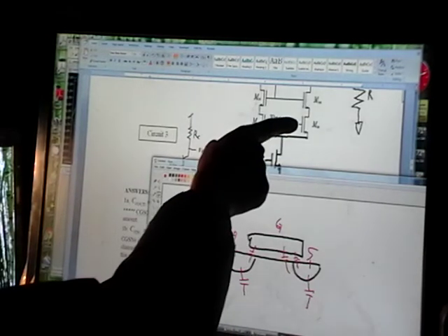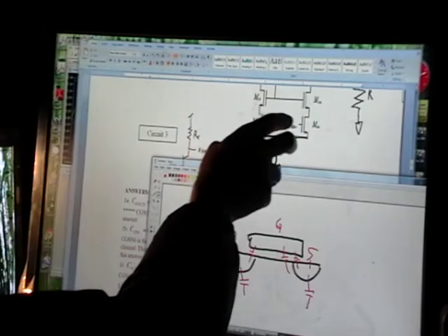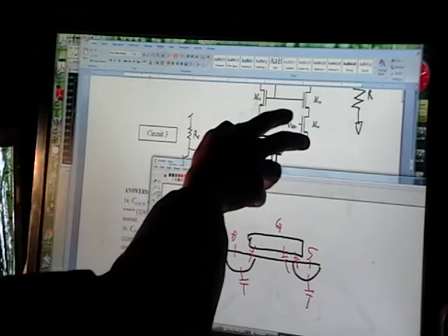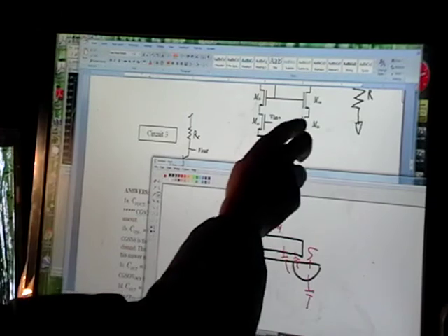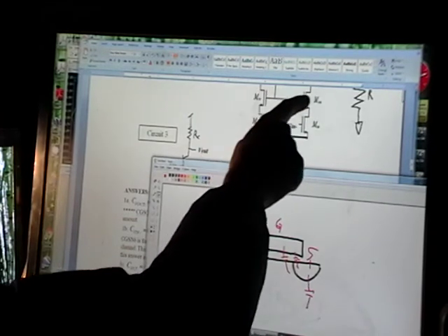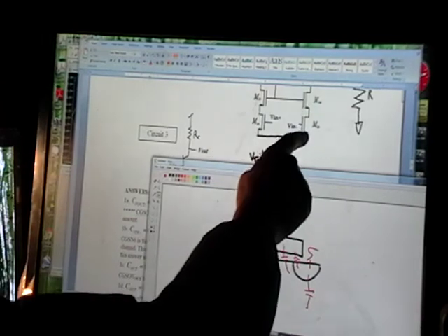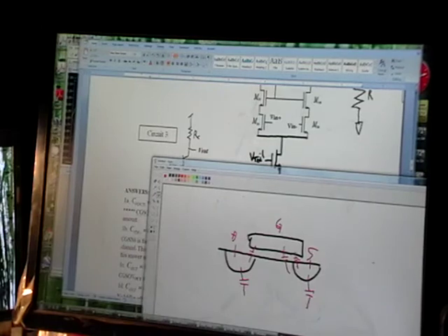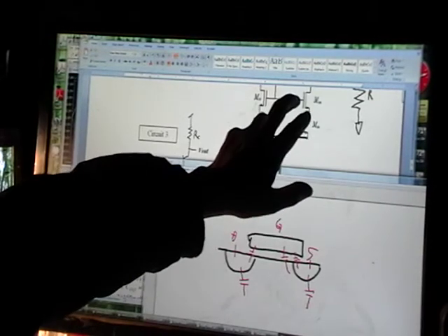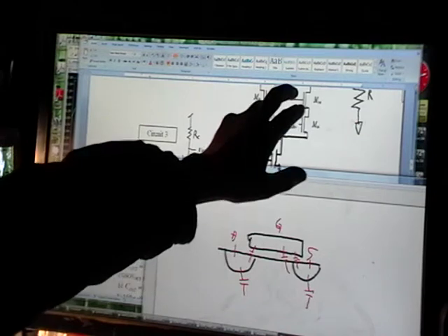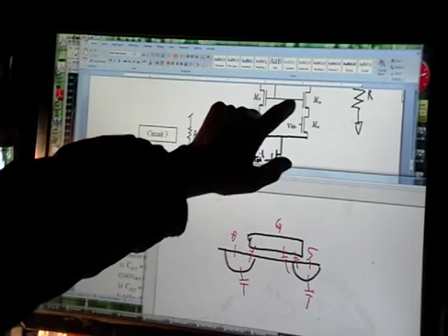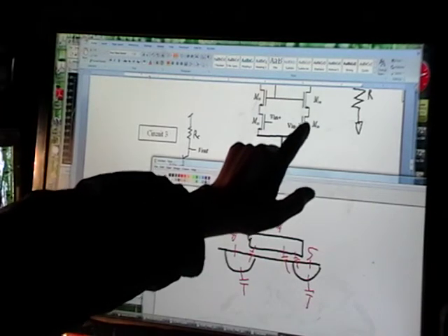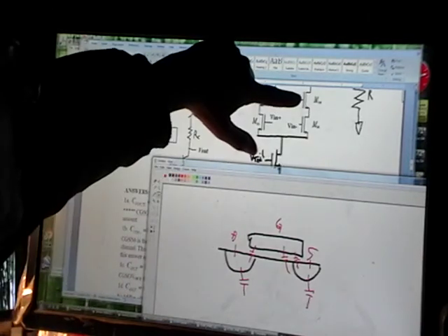And in the cascoded case, when V in minus goes up, that's just changed the VGS of this transistor. Okay, so if this goes up, VGS increases, the current through here increases. Now this transistor here, it's got a DC voltage on its gate, but since the current through it's increased, physics takes over, and physics moves the source voltage down to increase the gate source voltage to the same thing as this. So if you move V in up, VGS of this transistor is increased, the current through here is increased, so the current through this transistor is also increased.